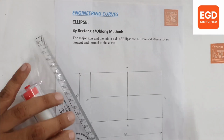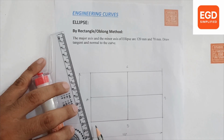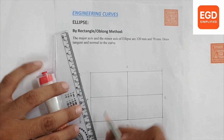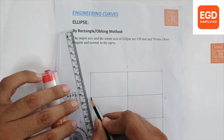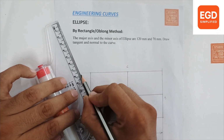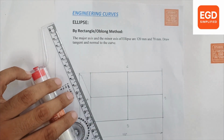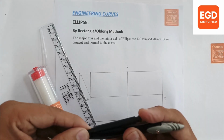After constructing this rectangle, we will divide these three lines into equal parts, let's say 3 equal parts. So divide this line into 3 equal parts. We will draw a line which is less than 90 degrees, then take a small measurement.